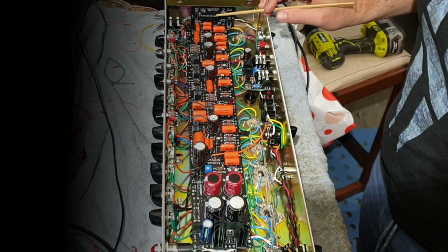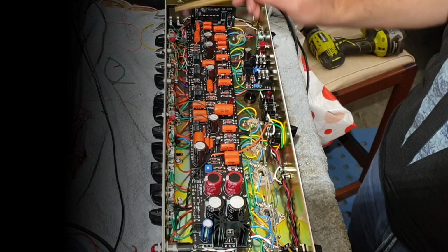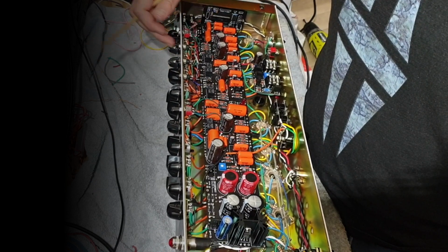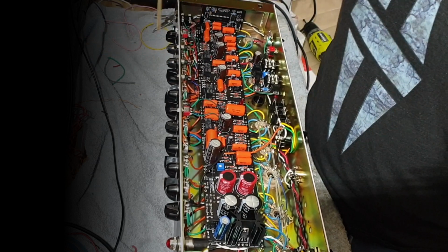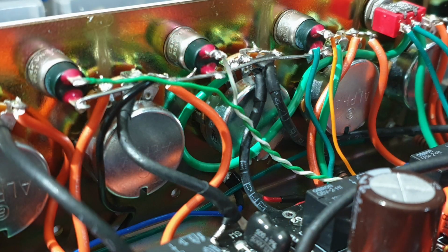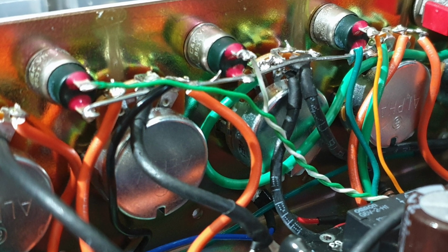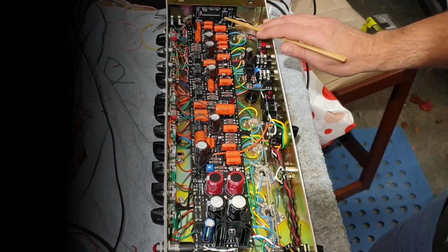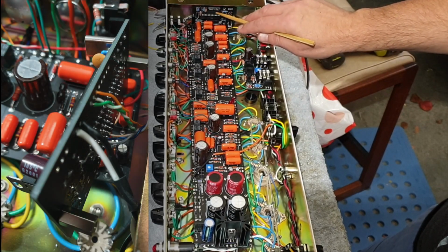A couple of things I need to tell you about with this MIDI board. These three momentary switches here are soft button mini switches. This is the momentary ground. You can see on one side of the switch, at the bottom, I've got a bus wire which connects to ground. And then I've got three wires here, green and white and orange. They are running to toggle. So I've got toggles and channels. The toggle 1, 2, 3 on the MIDI board here.